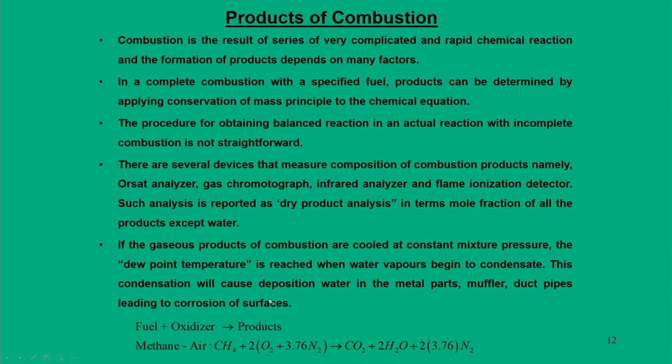So, basically all combustion products, if you look at CO2, nitrogen and so on, except water, the analysis we do, we call this a dry product analysis in terms of mole fraction. But what happens to water? Here the question mark comes in.